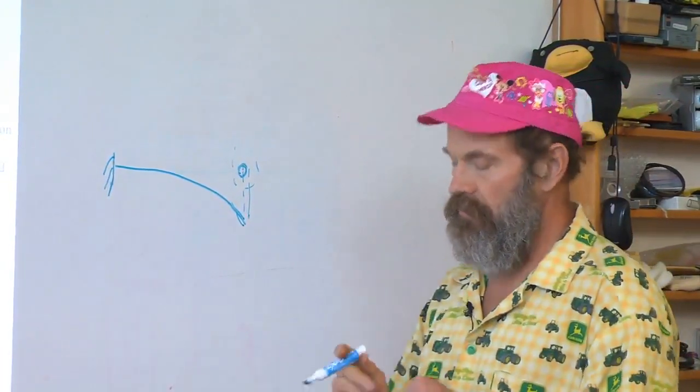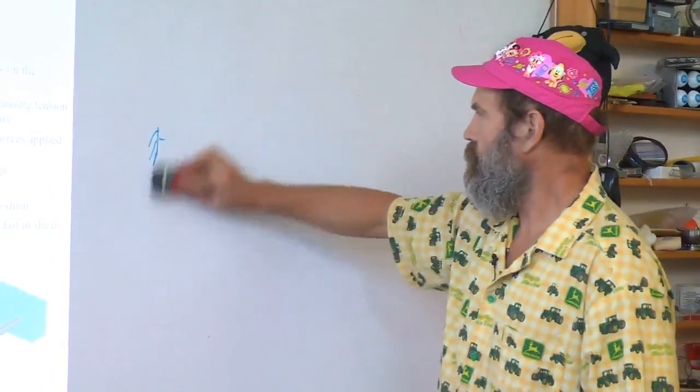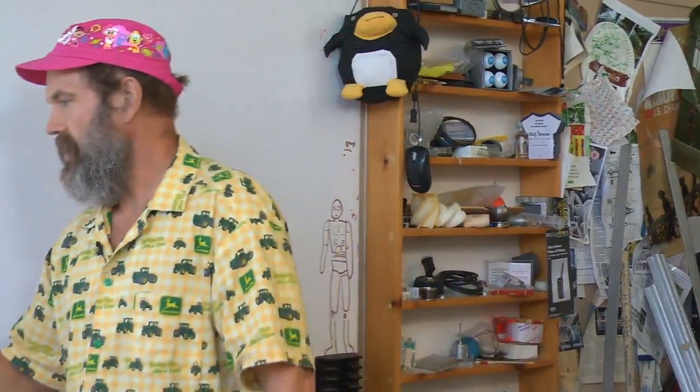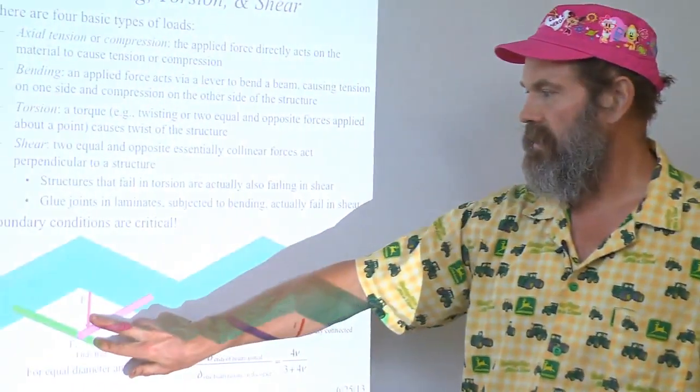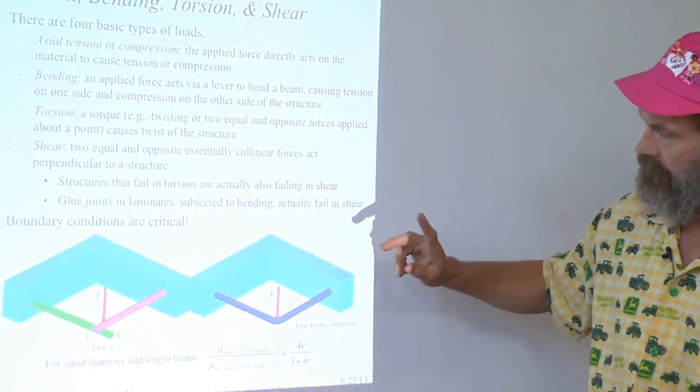The lesson here, on this level of detail, is that you start thinking about manufacturing and whether you use discrete elements or should elements be formed and then attached. It may seem simpler sometimes to use two simple parts and connect them, as opposed to one part that I had to bend.